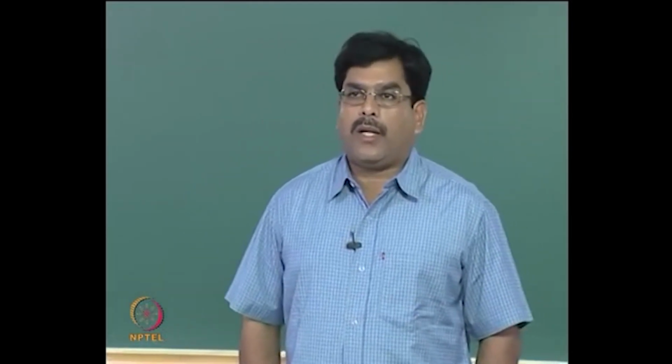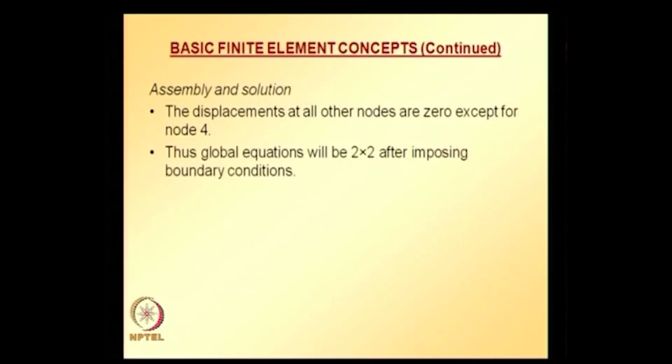Here node 1, node 2, node 3, all degrees of freedom are fixed. So, the corresponding rows and columns can be avoided. So, actually the contribution to the reduced stiffness matrix will come from the fourth quadrant.